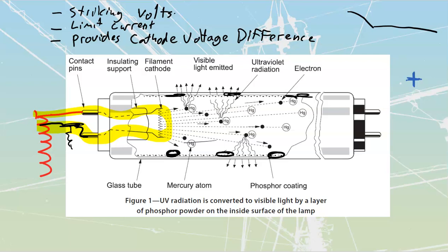All right, ballasts themselves are going to last a ridiculously long amount of time because they're just simple transformers. Some of them do have small switching components, particularly this cathode preheater, but that's usually a plug-in extra that goes onto the ballast itself. The actual ballast itself is just wound. If it does get too hot, like any other transformer, you run the risk of VOCs degassing.